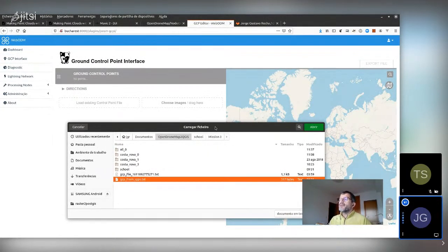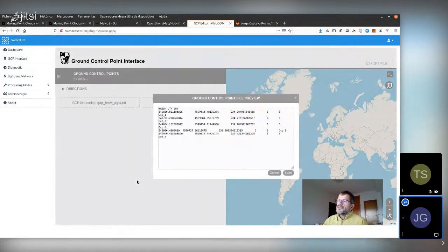So with these ground control points, you make sure that you can have better georeferenced data. For example, when surveying these ground control points and comparing to Google Images or Bing Images, you always get bigger errors. It's not difficult to have 1 meter error, usually below that, but 70, 60 centimeters error are common in Google Maps and Bing Maps. So georeferencing using those sources will not give a very good model.